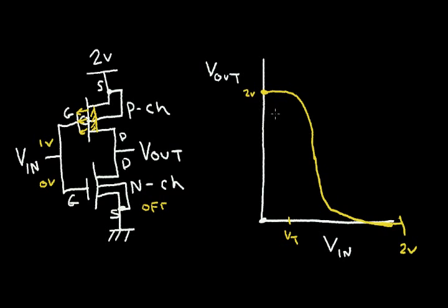So this is called the DC transfer curve. And it's a plot of the Vin versus Vout. And the significant thing is that in this part of the curve, we're drawing essentially no power dissipation. And in this part of the curve, there's no power dissipation because both transistors are off. Now, when both transistors are on for a brief time, when things are switching, we get a current. If I plot the drain current, I'll get a spike of current, something like this, where this is the I drain, or the current flowing in this branch, I drain.